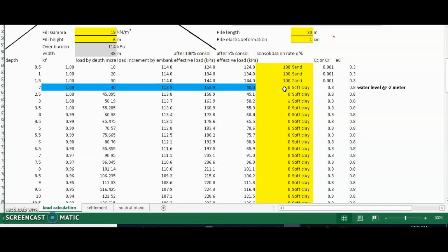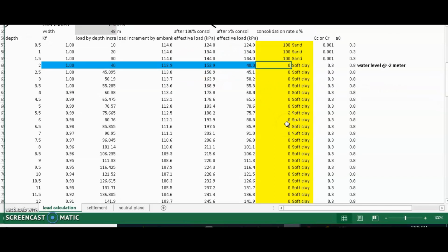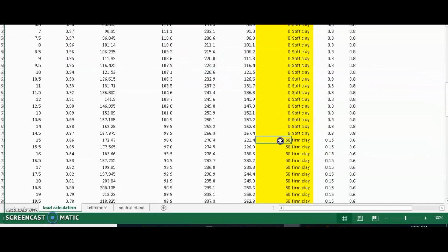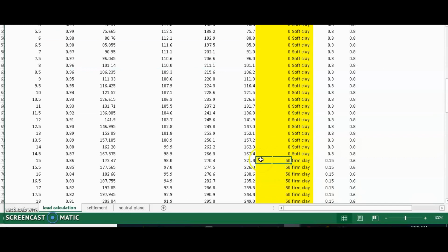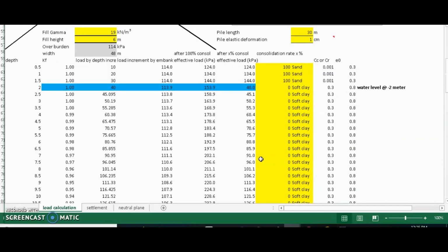With a starting point of 0, your settlement happens from 0 degree of consolidation to 100%. If your clays are in some over-consolidated condition, having previously reached some pre-consolidation pressure, then maybe only 50% of the consolidation degree is your starting point.